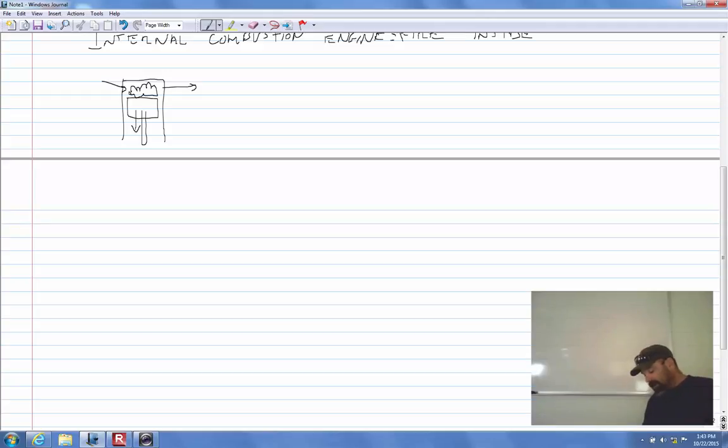So now we talk about climbing hills. Before, we were talking about flat ground with no headwind or anything like that. Now gravity falls into play, right? Because we're climbing a hill. Again, we know the formula for figuring that out: mass times gravity times height. Here we're talking about climbing a 1 in 20 hill, which means for every 20 meters forward you go, it climbs 1 meter. And that's 100 meters high.